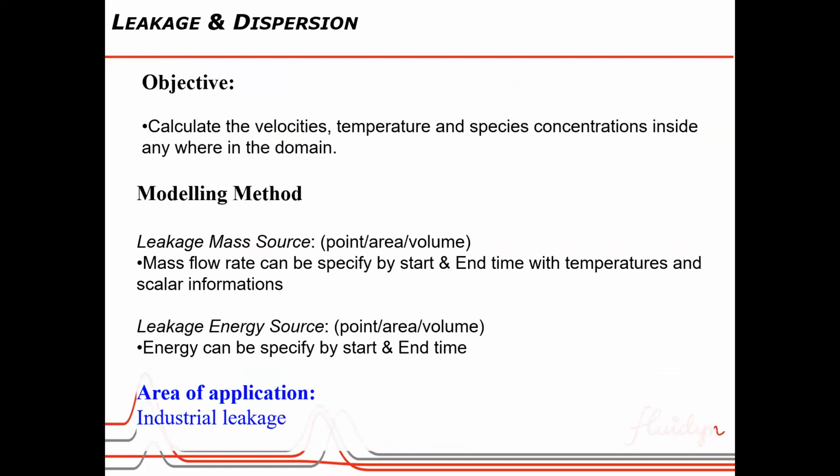In addition, we can see how the concentration is transported across the computational domain. From a leakage point of view, suppose you have a gas entering at high temperature, then we can specify that energy as a rate or as a mass flow rate, with a start time and end time, at certain temperatures. It will be emitted in the defined directions.